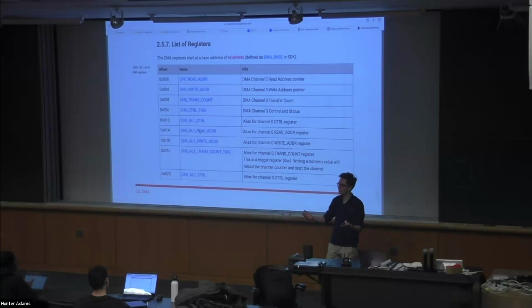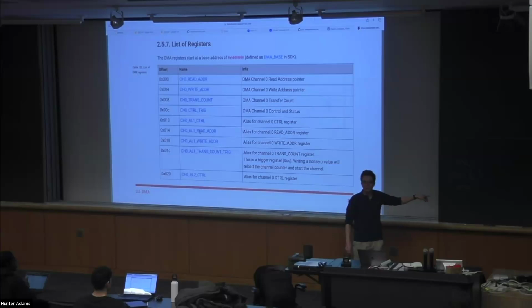In lab 1, we were using a timer interrupt and the direct digital synthesis algorithm to produce sound. That has the advantage that we can build a synth. We can dynamically at runtime change the sounds that we're generating because they can be functions of some equation that we're evaluating in our code. We're not doing that here. We're producing a single sound, but the advantage of this is we're spending 0 CPU time to produce this sound effect.